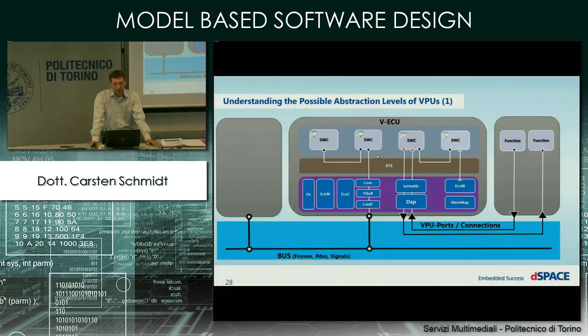So if they are located on different ECUs, for example, there would be a software component here, they typically communicate over a bus. And so technically, the communication goes through the communication stack. So that is this kind of base software modules here, and then going over the bus to the next ECU, and then going up this way, and then you have this communication over the bus.